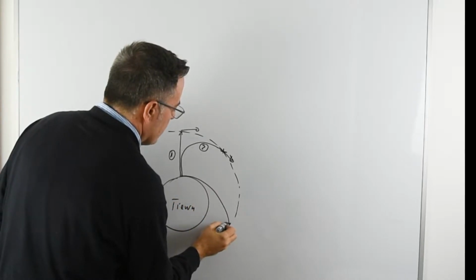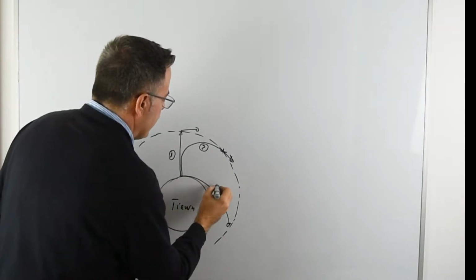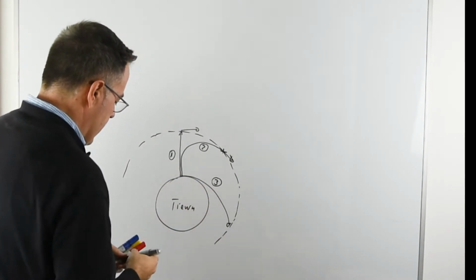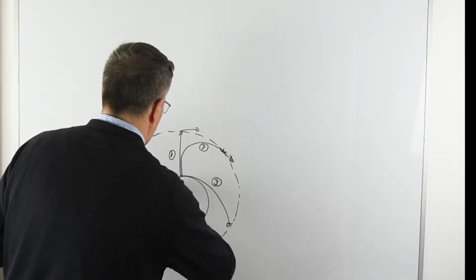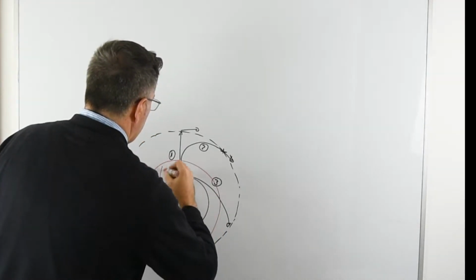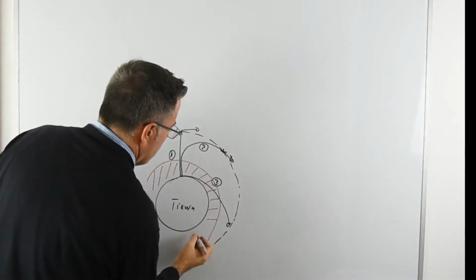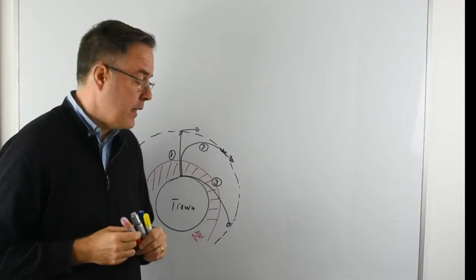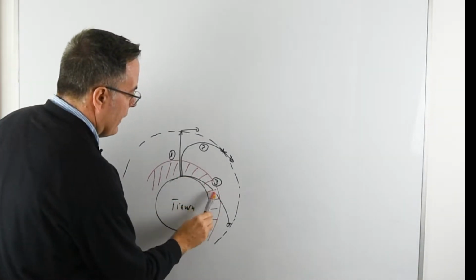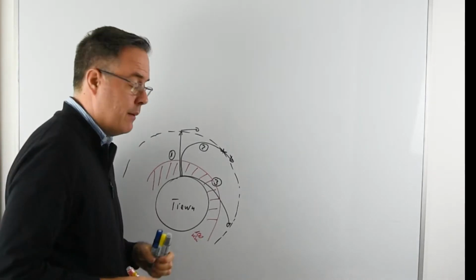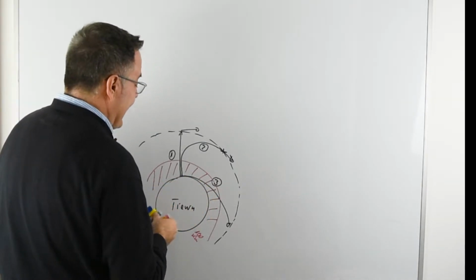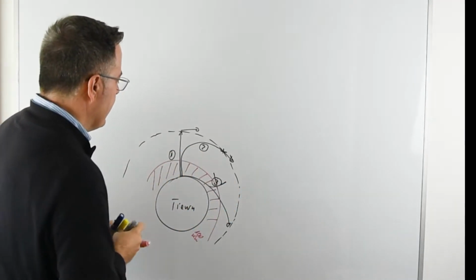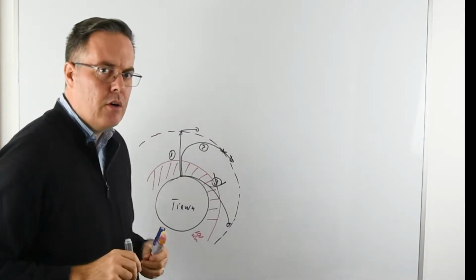Then a third option that could be, let's imagine, more efficient, as we launch the rocket horizontally in order to avoid the vertical component, and it seems to be much more efficient. But if we remember, we have the 100 kilometers thickness of the atmosphere, and in this third option we are going to travel quite a lot of time with high friction with the atmosphere, and that means it's going to be anti-economical, let's say too expensive. So we dismiss this third option, and then let's focus on the first option.